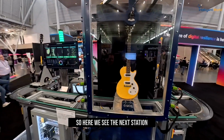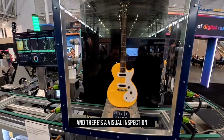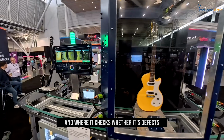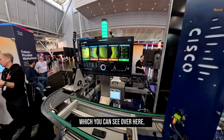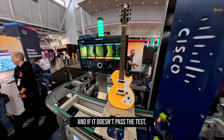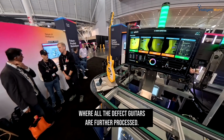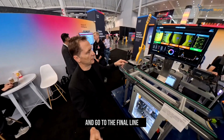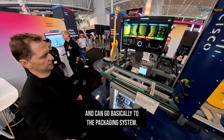So here we see the next station where we have a visual inspection. So you see a scratch over here on the yellow guitar, and there's a visual inspection depending on the different type of checks that are done, where it checks whether there are defects or whether it can pass the test with all the visual inspections, which you can see over here. You can see the yellow one has a scratch, it's detected, and if it doesn't pass the test, it's going to the separate line where all the defect guitars are further processed, and the ones that passed go to the final line and can go to the packaging system.